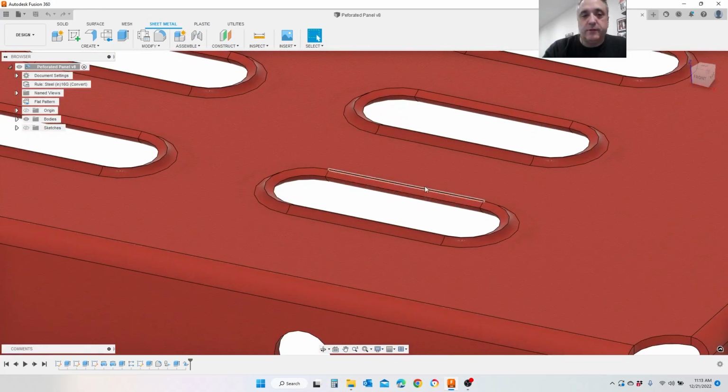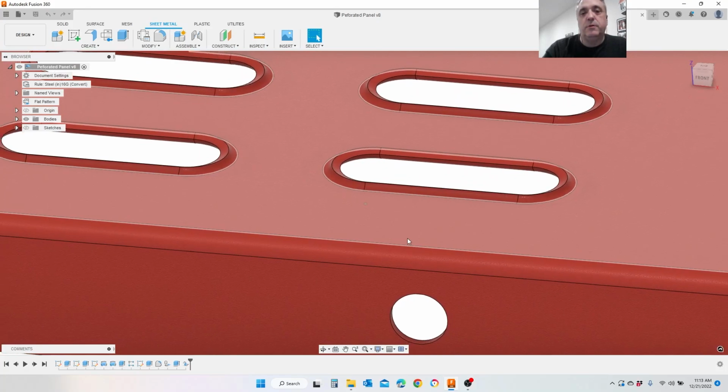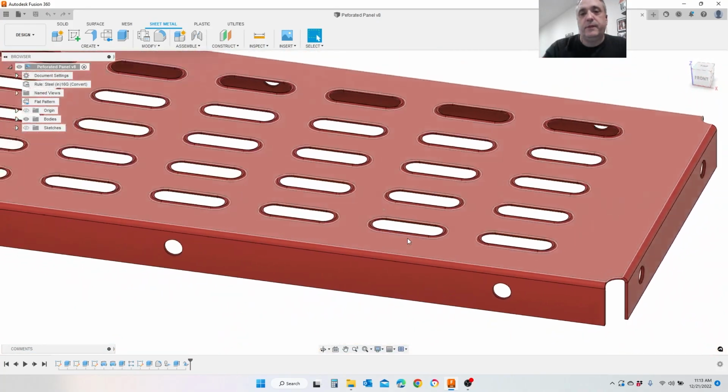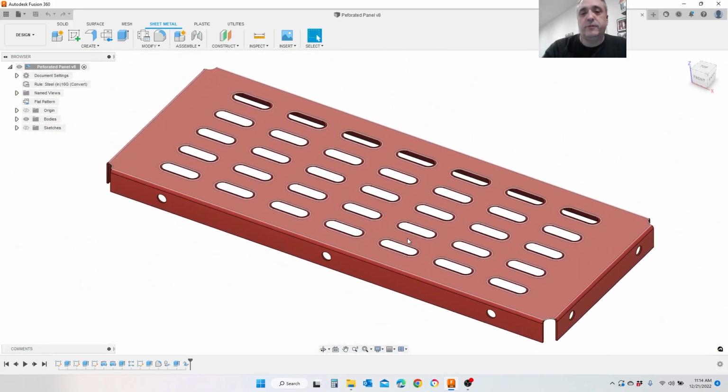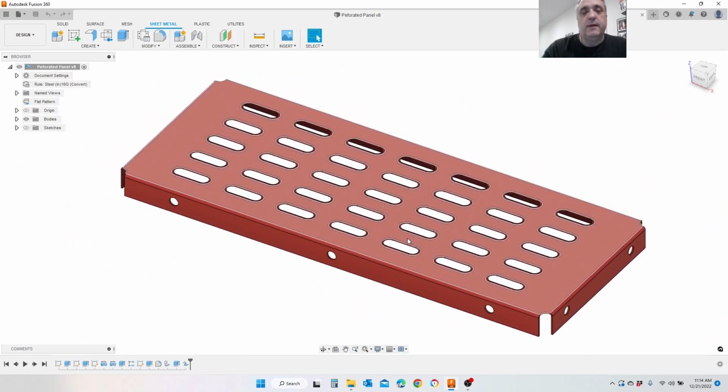And specifically, you can see these perforations are knurled up a little bit. That's a common type of feature that you might want on the design in sheet metal. And you have to actually do a workflow and modeling to do this. There's not a tool right now in Fusion that can actually simulate this.